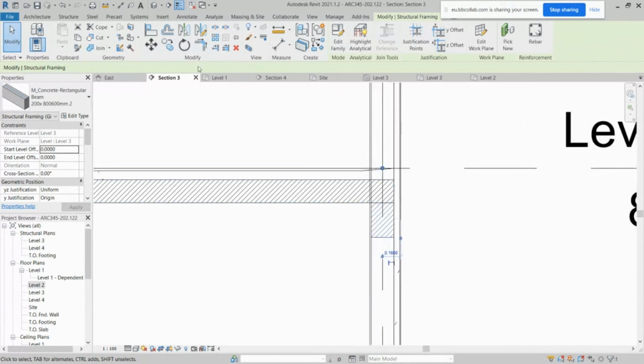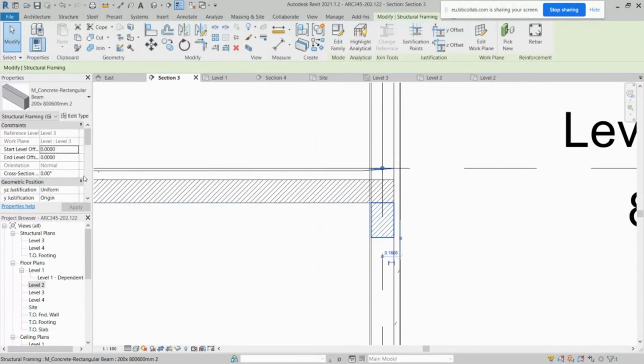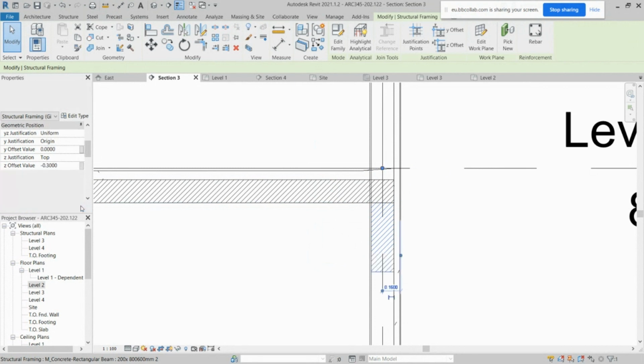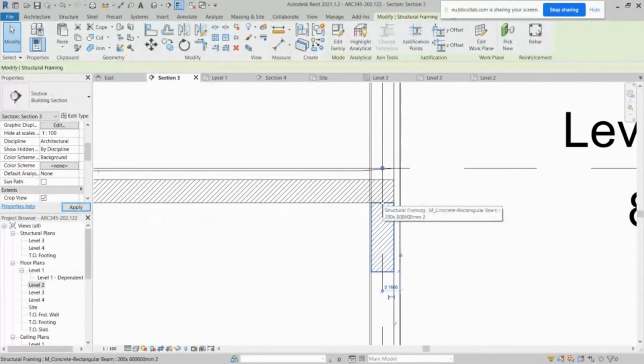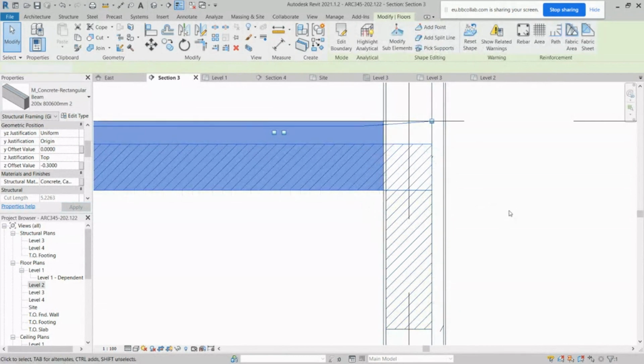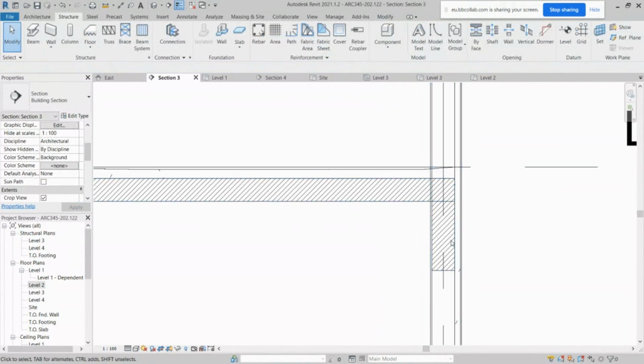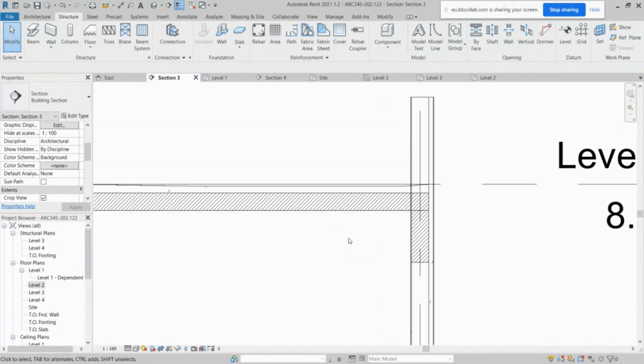So what we can do here is measure the dimension from the elevation up to the slab bottom, which is 0.3, and then start our beam after that. So we come to here and we offset that. The Y or Z offset, I think it's the Z, 0.3. Then apply, so we see that now the beam line is here, and that is the slab line. You see the difference between them, so they are not overlapped with each other. Technically, you can start your beam from here and go down. That is not a problem, but you better avoid having the overlapping, as we see.